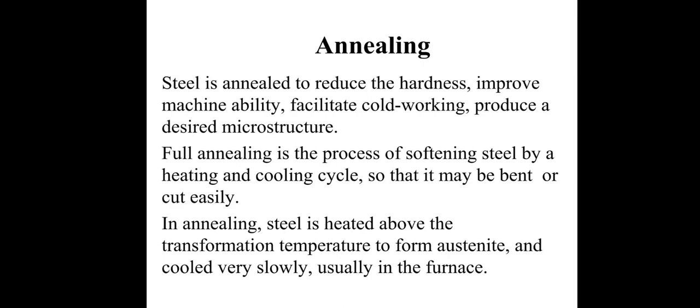Annealing is a heat treatment for the general purpose of softening or stress relieving a material. Steel is annealed to reduce the hardness, improve machinability, facilitate cold working, and produce a desired microstructure.